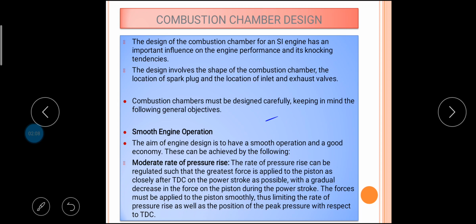minimum pressure drop. Any design of the combustion chamber that improves its anti-knock characteristics permits the use of a higher compression ratio, resulting in increased output and efficiency. A compact combustion chamber reduces heat loss during combustion and increases the thermal efficiency. Different types of combustion chambers have been developed over a period of time. Some of them are shown in these PPTs.